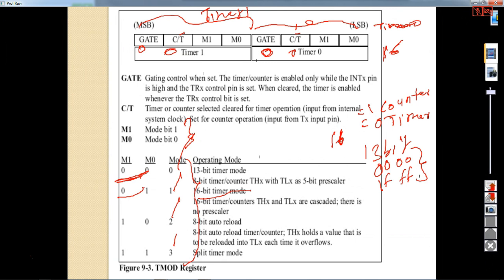The registers, you can use them as, let us take TL0 and TL1, and TH0. You can use it as an 8-bit register, an 8-bit counter. But in mode 0 and mode 1, once the timing or counting is done, you have to reload the value into the registers.